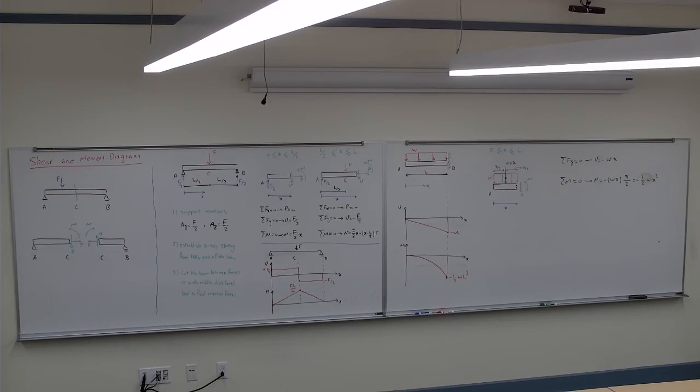Any question? So just remember, when you're dealing with the distributed load, do not replace it with the single load until you cut it. After you cut it, replace it with the single load, but not before.